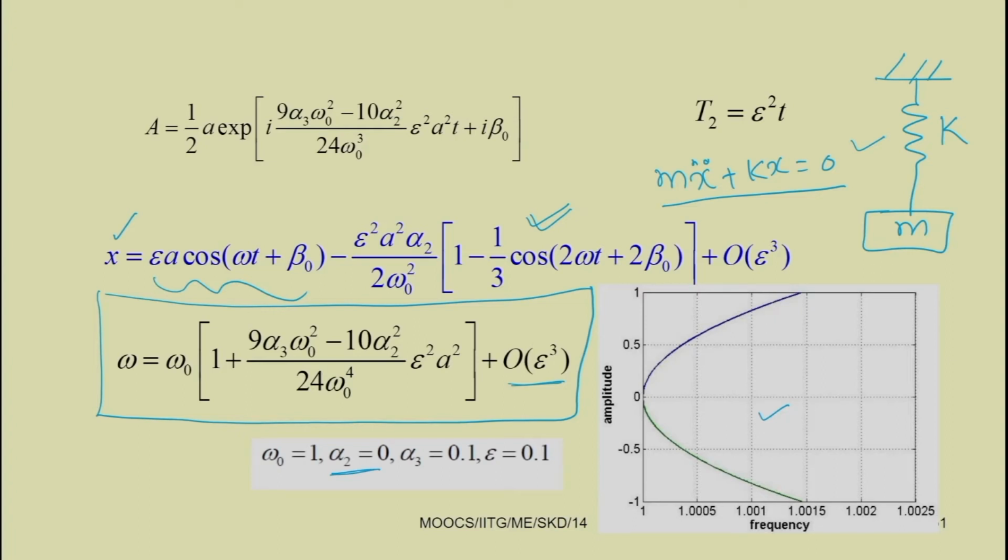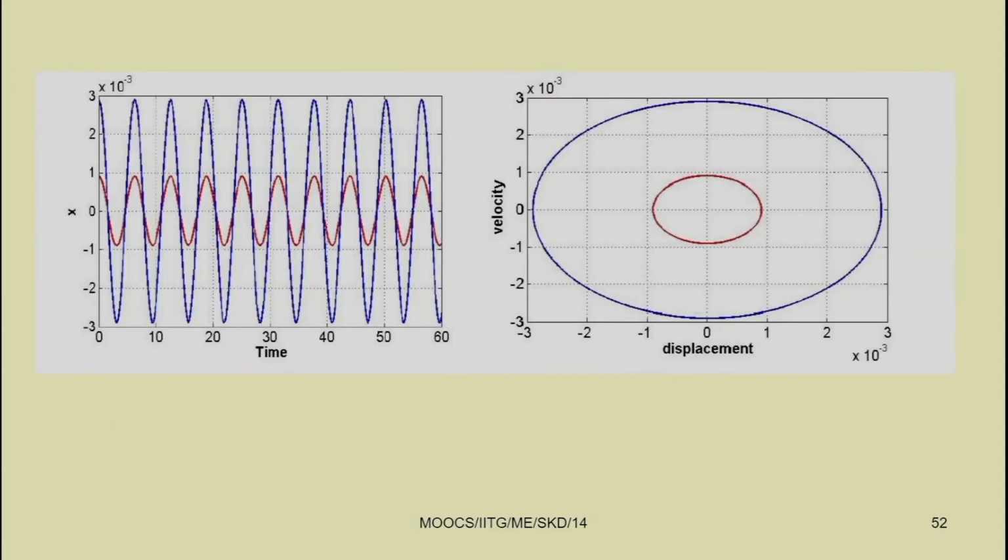but in case of the simple spring mass system with m and k, we have constant values of m and k, so we got this omega does not depend on a. But in this case, for a different value of omega we have a different value of a, and we can find this response using this expression. So, by taking different initial conditions, if we plot this,